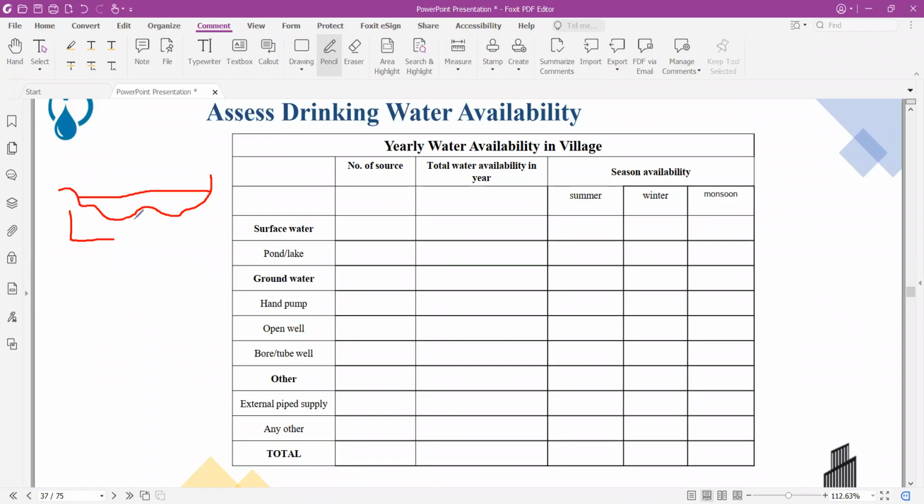The cross section at a specified location can be determined using different methods like a total station or a level. The width can be calculated. Similarly, the depth at different locations can be calculated, and by taking the average depth and multiplying it with the width of the river, we get the area.